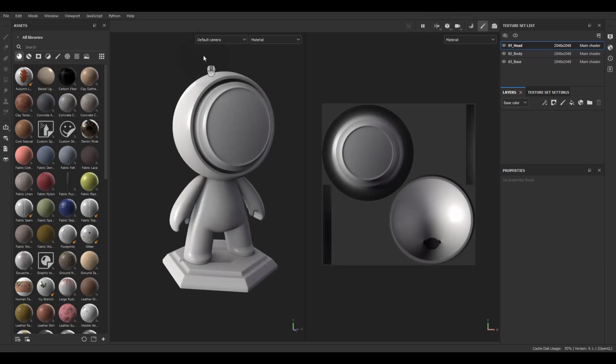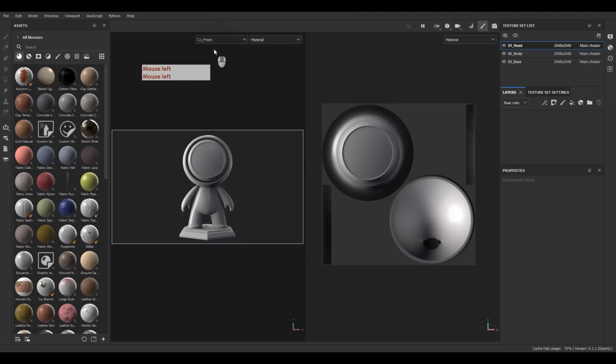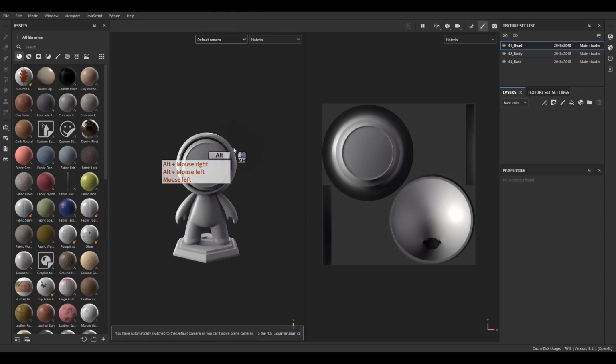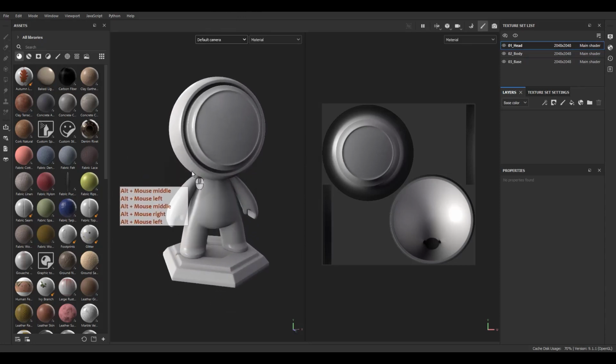As you can see, we have a list for the camera and we can select among the cameras that we set before in the 3D modeling software. For example, in 3ds Max or in Blender, we set the camera and we export the camera with the FBX file. And when we import the model inside Substance Painter, we check, okay, we have the camera, and let's please import the camera for us. And after that, we can control which camera we can see inside the 3D viewport.